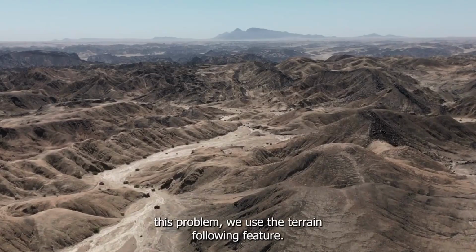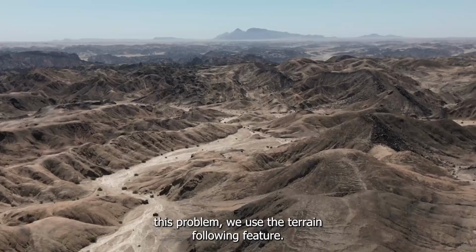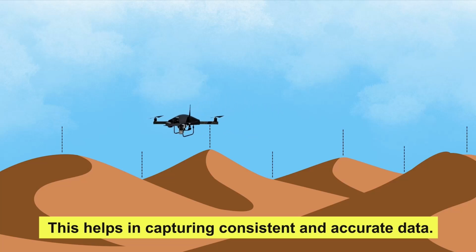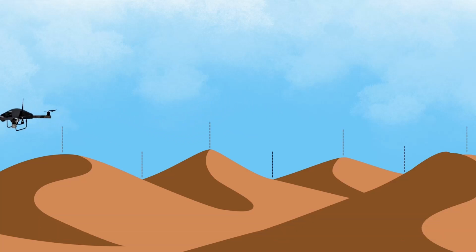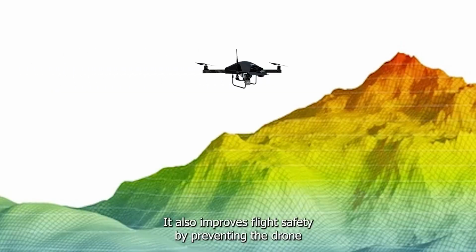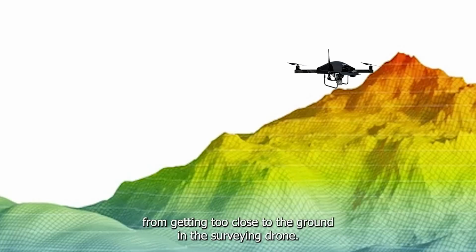To solve this problem, we use the terrain following feature. Terrain following allows the drone to maintain a constant height from the ground throughout the entire flight. This helps in capturing consistent and accurate data, especially in hilly or uneven areas. It also improves flight safety by preventing the drone from getting too close to the ground.